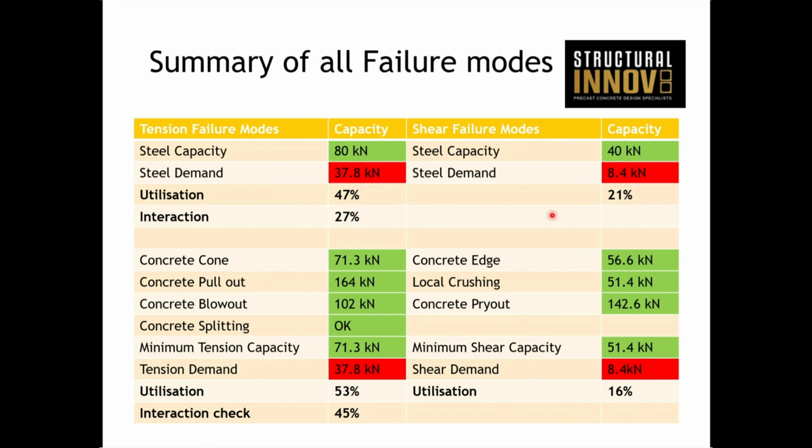So when you bring all your numbers together then, because we were lifting, we had tension forces and we had shear forces. So we got to check both and we got to check our interaction. By doing that, you can see that it all works out. So the lifting on site wasn't the most governing of cases. It was more tilting and demolding that would govern this design. So we gained on the concrete strength and also the position and depth of the lifters as well.